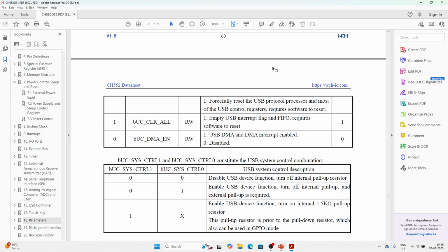So if we are using any voltages within 3.6 as its VCC, then the VCC should be supplied with that, and external LDO needs to be put in, right? So that we have both the VCC, which is the voltage below 3.6, and the LDO gets 3.3. The internal LDO will not support at that particular point.